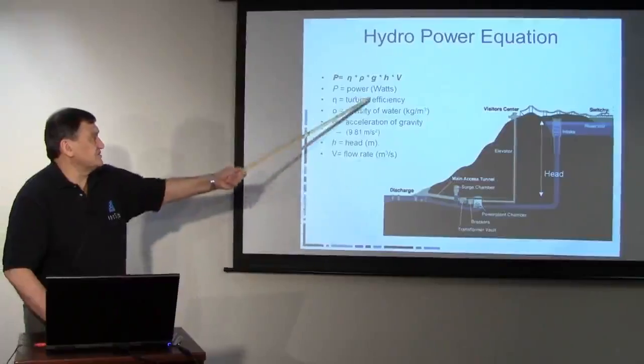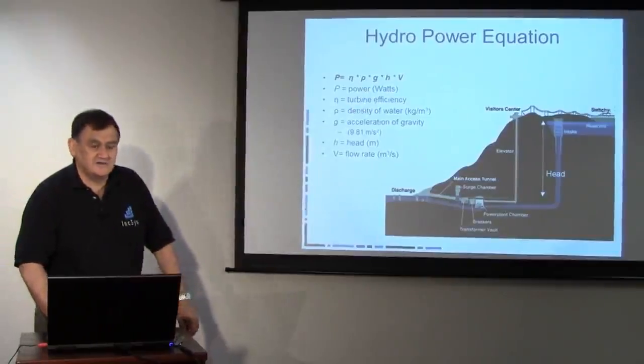Individual plants may have local computers that are actually dispatching all the individual power plants, or hydro units. A hydro plant may have anywhere between 2 to 4 to 10, which is quite common, but as many as 20 units, all running with their own penstocks and their own turbines. And there's often a local power plant computer which is figuring out the actual dispatch of the total requirement that you as a system operator asked for, and making sure that those turbines are all running at the most efficient point. And the efficiency itself can vary with the power that it is generating.